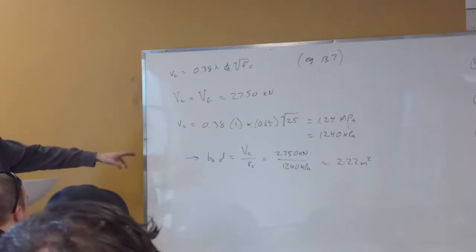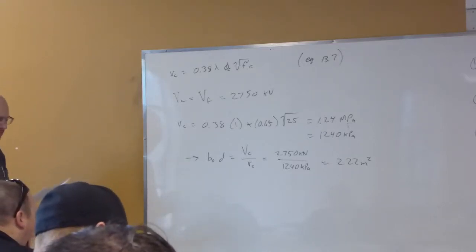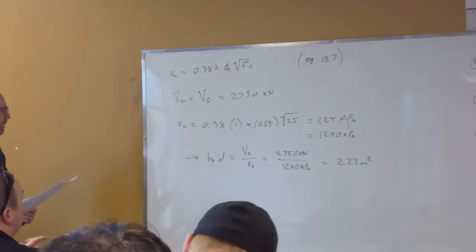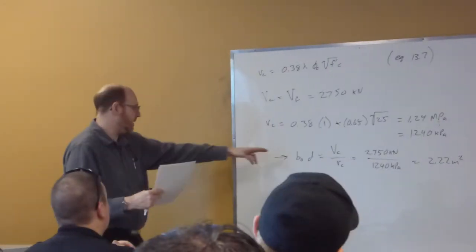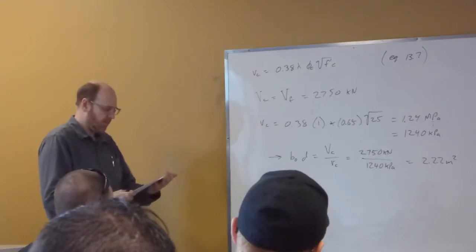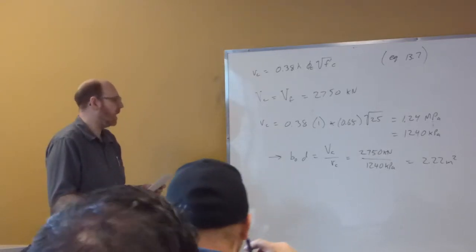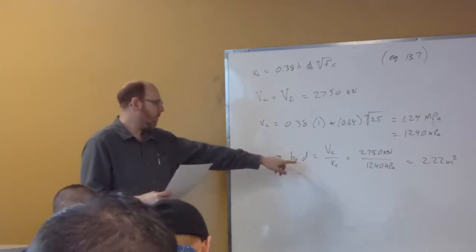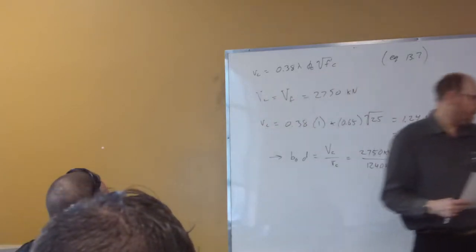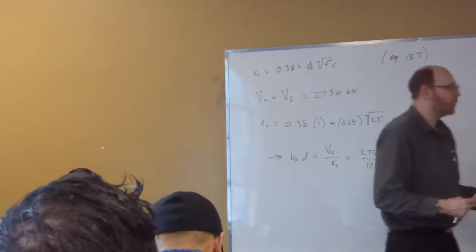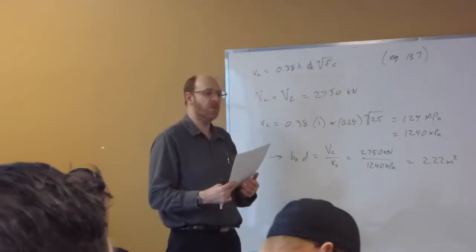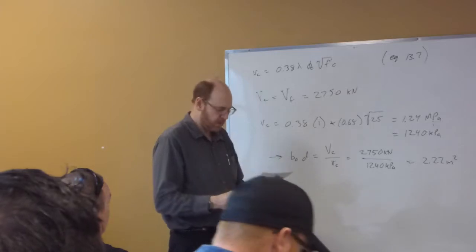Now what we've done here is we've isolated the V0 term, the parameters that relate to the geometry of our footing. Remember that for our two-way shear, this is based on d. Not only is it based on d here, but our b0, that perimeter that we were talking about, is calculated at a distance of d over 2 from the support.